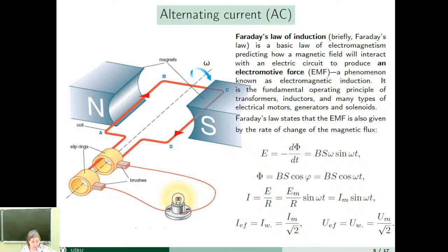For the characteristic of an alternating current, the concept of working or root mean square value of current is introduced. The effective value of alternating current is defined as that steady current which would develop the same quantity of heat at the same time in the same resistance as done by direct current. And look at this expression.